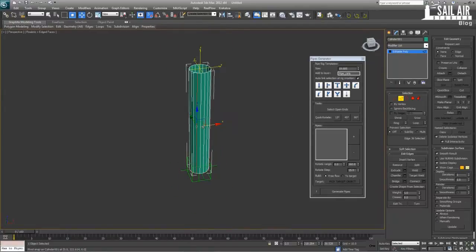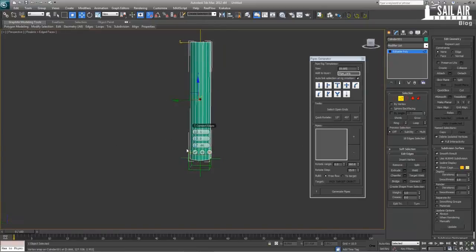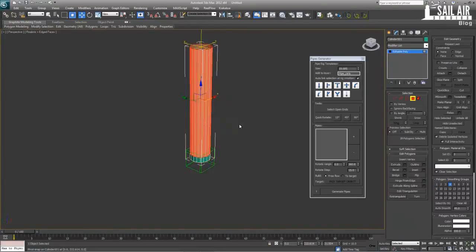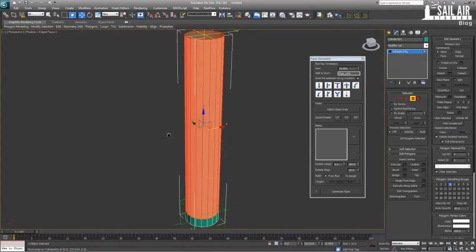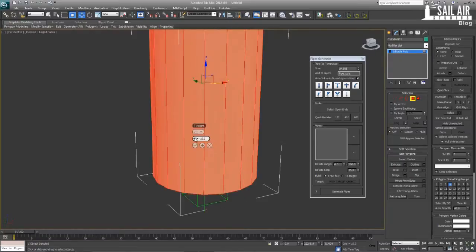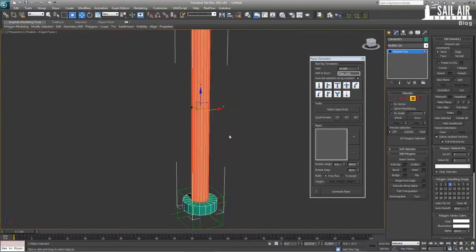So if I ring around, let's ring and connect. And let's put a slide on it. I don't really care too much about exact amounts. So let's slide down to about 90. As you can see, it's down there right now. Press OK. Click that, and then Shift Select. I'm going to turn snapping off by pressing S. Shift Select this so I get all those around there. Extrude backwards, so go by local number, and back to about negative 2.5. And so there we got.